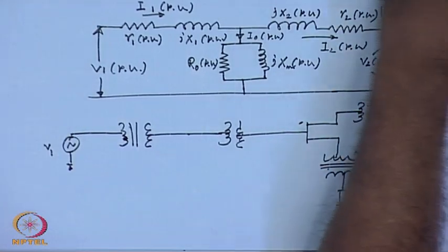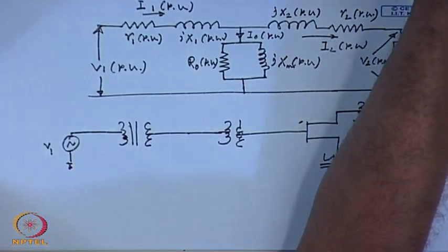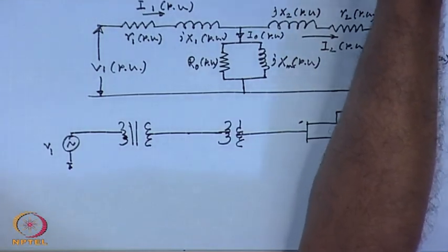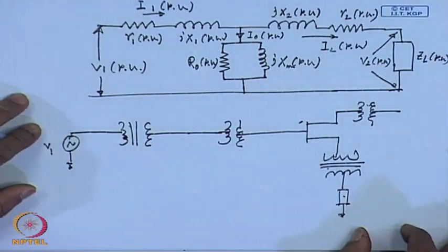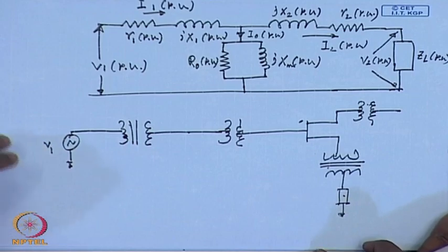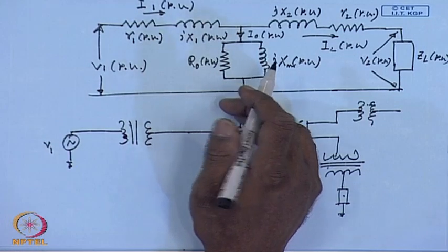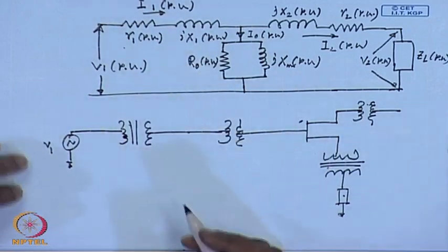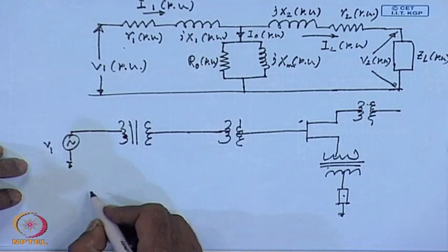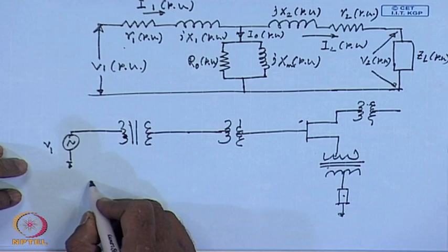Therefore, for almost all practical calculation, the transformer parameters are normally represented in per unit. In fact, just as with exact parameters, the approximate equivalent circuit of the transformer can also be drawn in per unit.